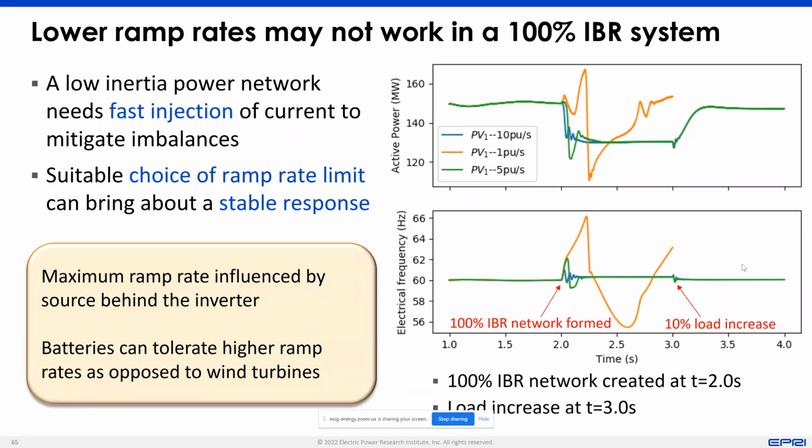What didn't make a difference in a strong system, or what didn't have an impact in a strong system, can actually be unstable in a weak network. And this is where it comes down to what was mentioned of also the time of delivery of service. So if you now, let's say as a planner, if you're looking at this network and trying to procure these various services, it's important to have a notion of how fast can this service be provided, because the burden of providing a service now might have to be split up across multiple resources.